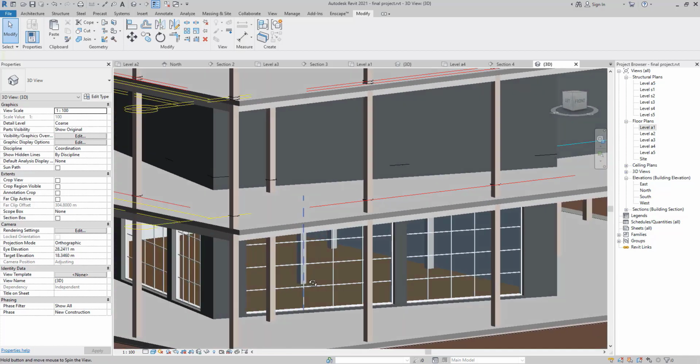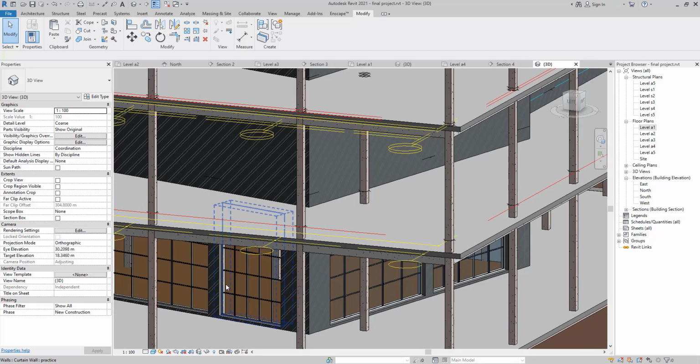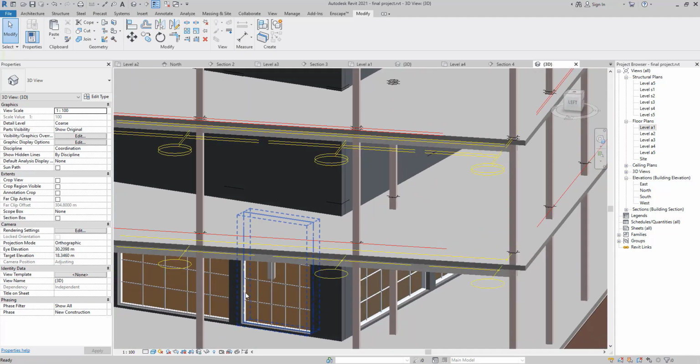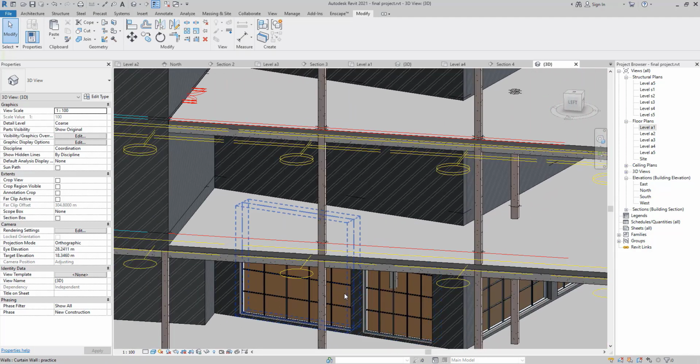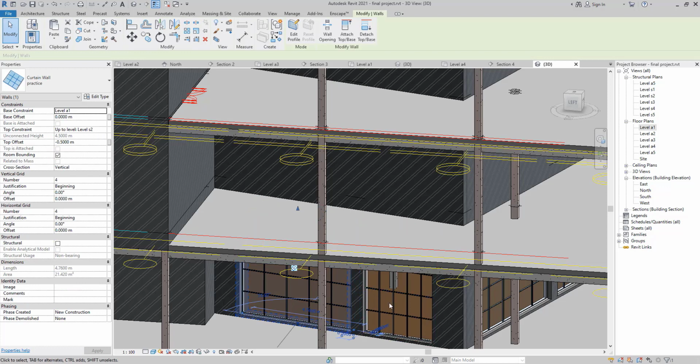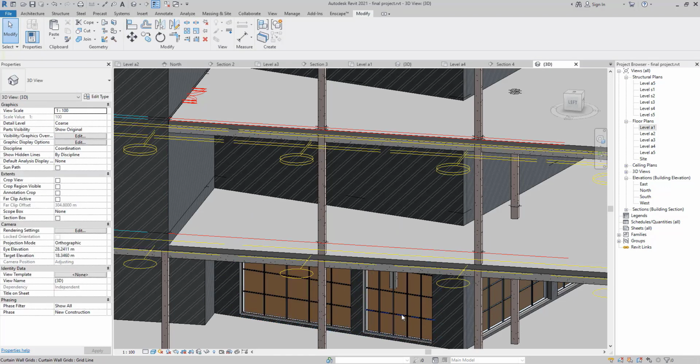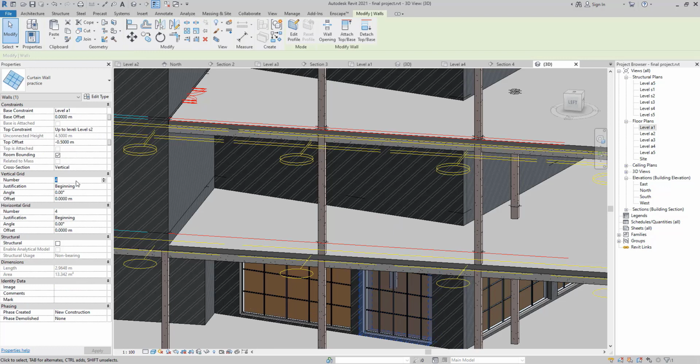The mullion is okay, everything looks fine, and we can change, for example, some of the settings here. Here there is a bigger opening than here, so we can consider 4x4. We can consider a smaller amount for here, such as half, so we can just use 2x2, apply.